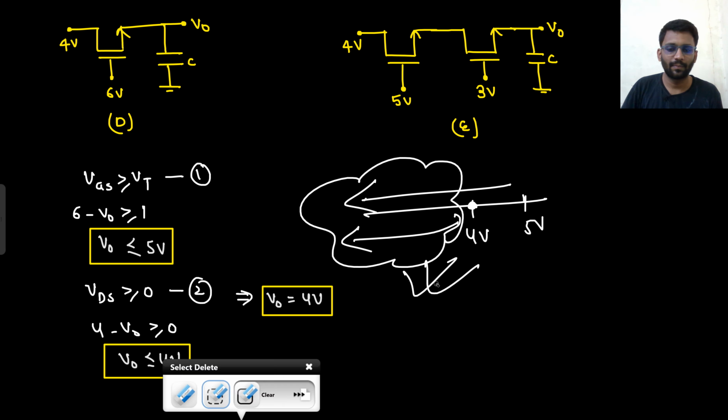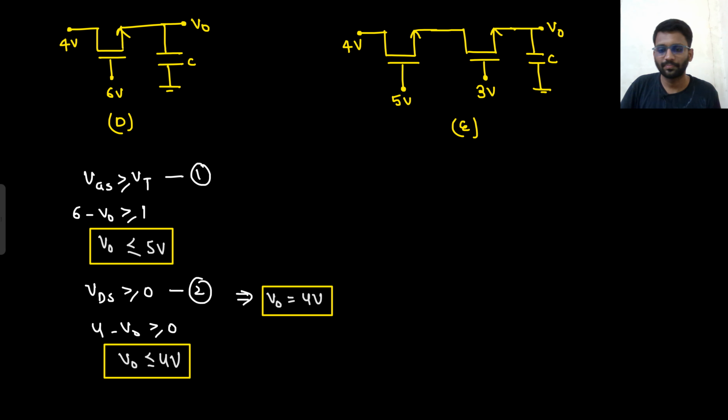Right? Now see this question. At every output you can assume some capacitor. Even if the capacitor is not shown, you can assume the capacitor there. So tell me till what point it will charge. If you see from here, it should charge up to 4 volt. And then you will see at the drain that it can supply 4 volt, and it is well and good.